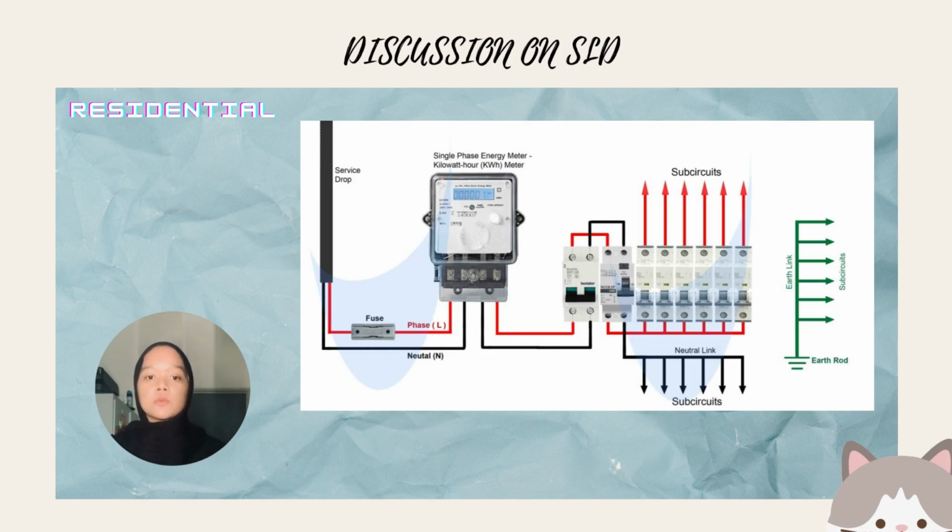My role is to briefly explain about the distribution board in residential areas. A distribution board, also known as an electric panel, is a component of an electricity supply system that divides an electrical power feed into subsidiary circuits. The electrical power supply comes from the network to the building through the main feeding cable. The cable is connected to the distribution board and the power is distributed through the breakers to the secondary circuits, which are lights and plugs.